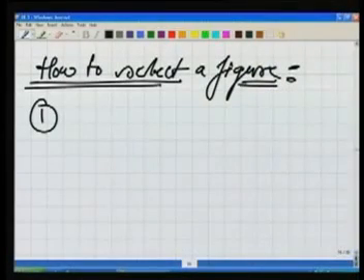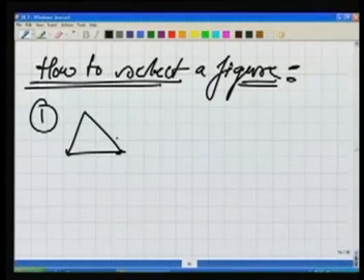But there are some points which we should keep in mind. Number one, a figure could be, as we have seen, only a single chain of triangles, a single chain of quadrilaterals, or maybe only one quadrilateral. If your area is 10 km by 10 km, you are going to make a map at a very small scale, 1:50,000, 100,000. In that case, only one quadrilateral can do. Or you may also go for, in some cases, a chain of quadrilaterals or a chain of centered figures. Many times all these figures may be combined. Here I am giving you an example of the combined figure.